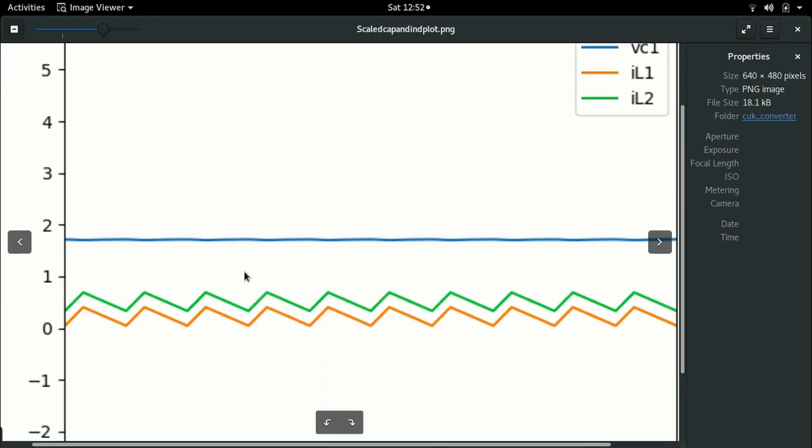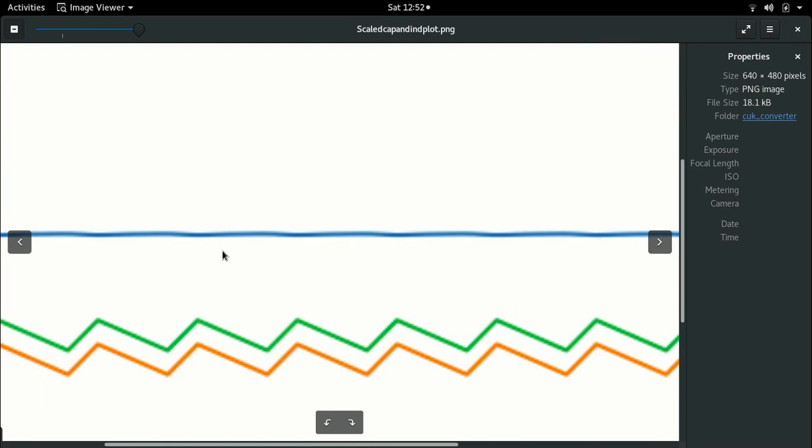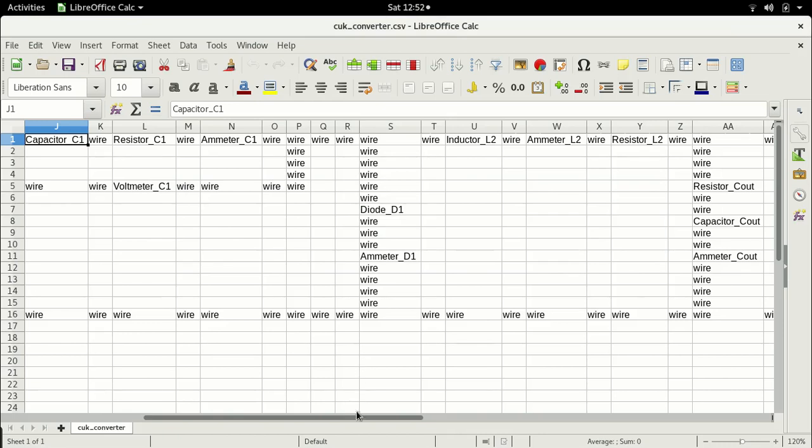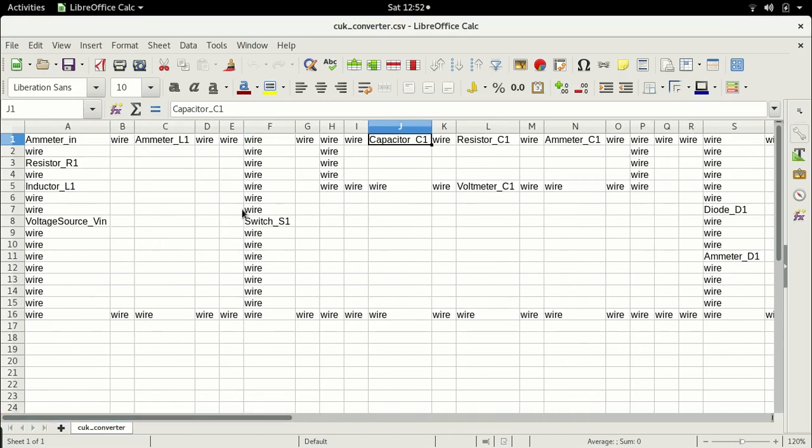Alright. Now, when the currents are falling, you will see that this output capacitor actually is rising by a very small amount. And that's also pretty obvious because you see that when the switch is turned off, the input voltage and the inductor are now charging the capacitor, which means the energy in the inductor is now being transferred to the capacitor, right?